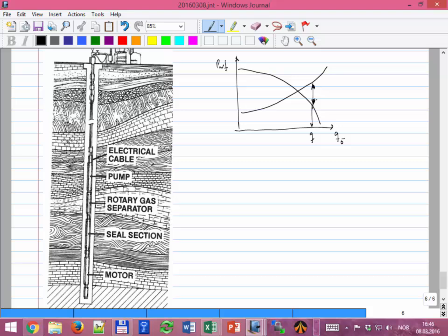And really this discussion is just to tell you what things we have to take into account, because the pump has a certain operating range, certain operating conditions, and you have to fall inside of this operating map. If, for example, your combination of rate and delta P falls outside of this map, then you won't be able to give that delta P at that rate. Then you have to go back, select another rate, get another delta P and check if that point falls inside or not. Okay, so we're going to have a short discussion on that.